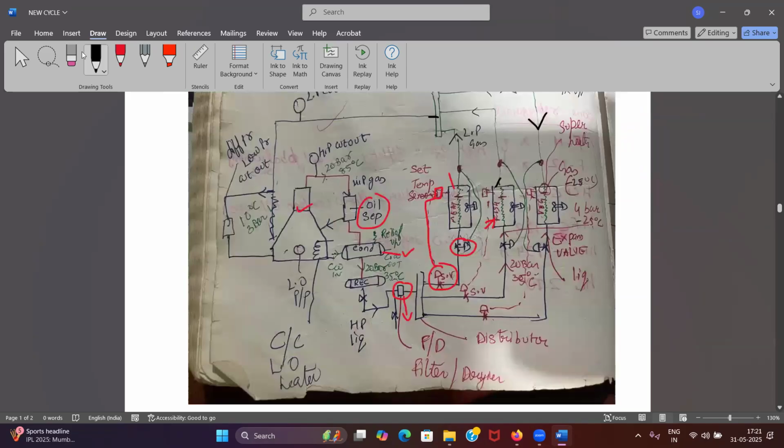Second is, now suppose my compressor has started or the system has started. Do I need the same amount of refrigerant flowing through A, B, and C? No sir, it depends upon room temperature. Okay, I want A and B to have more refrigerant flowing. Meat room, fish room, I want more refrigerant to flow because I want to maintain it at a much lesser temperature, -20, -18 degrees Celsius. Saturation temperature will be low, sir, for them. Yes. So I want more amount of refrigerant to flow into the system.